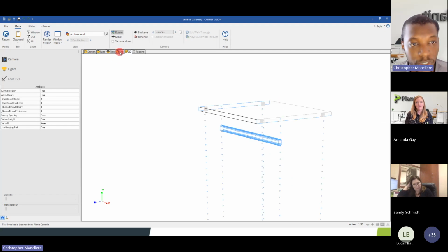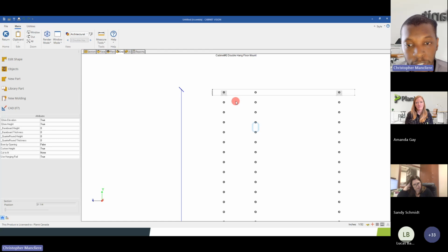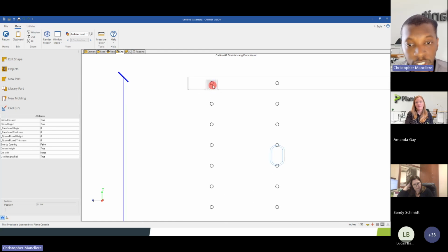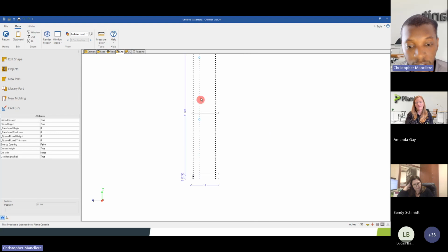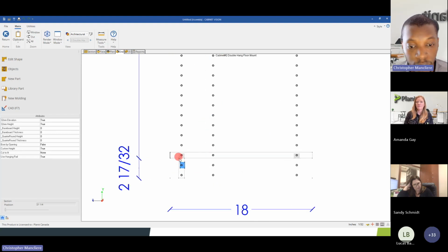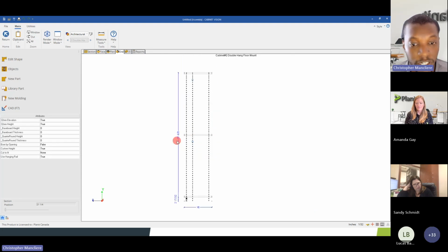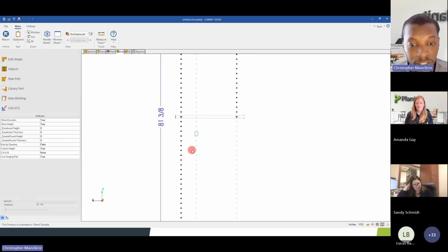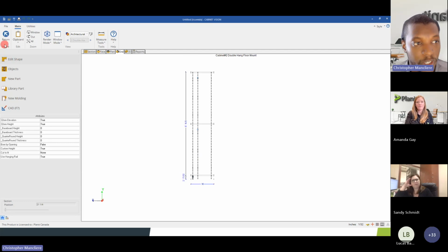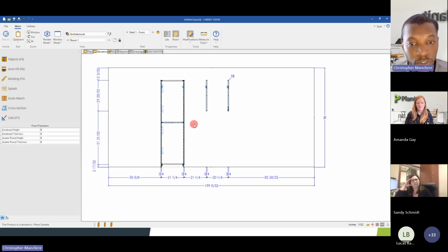And what I like with this one, if I go on the side, everything is following a 32 mil system. So virtually everything will always fall in a hole and then have all the parts to be assembled together. So I don't have to worry about how to drill it. I just drill everything and then I can assemble it and just look at the drawing and decide I have to put my shelf at a specific height from the floor and just find the hole that's the closest to this opening, for example. Same for the rod, it will always be able to be moved up and down as well. So that's what the closet would look like.